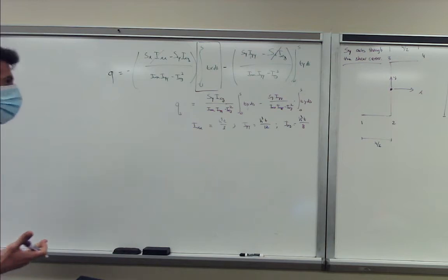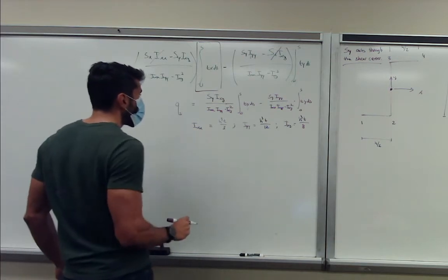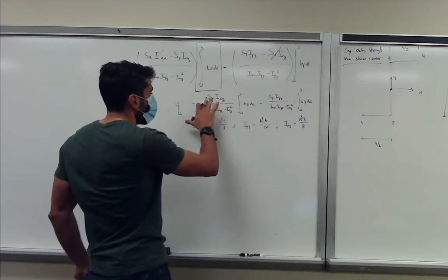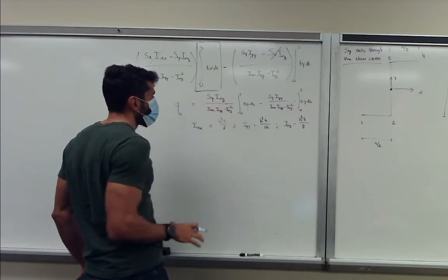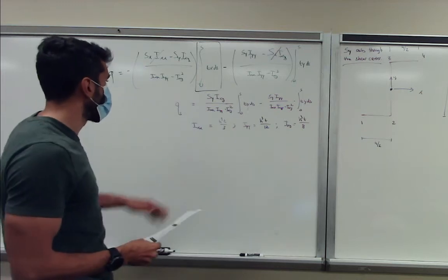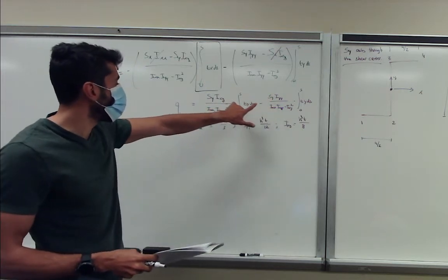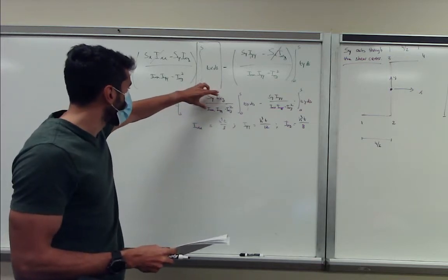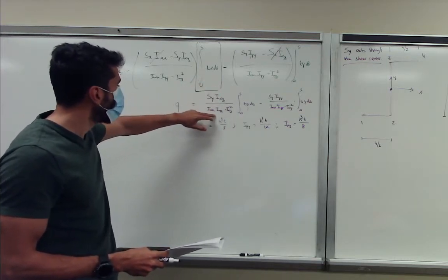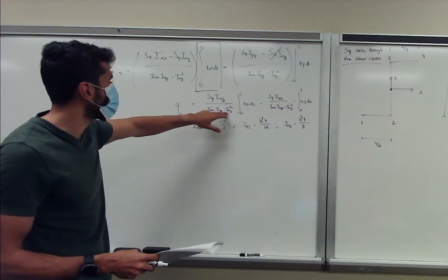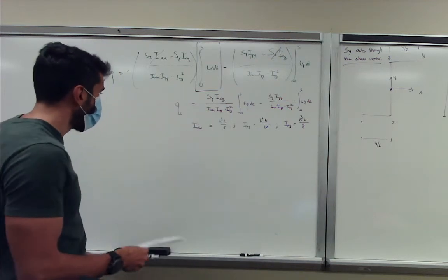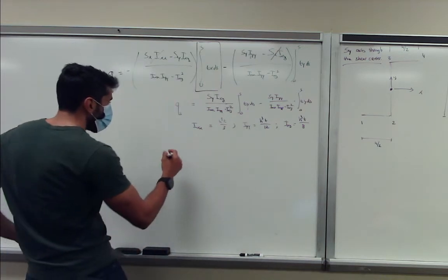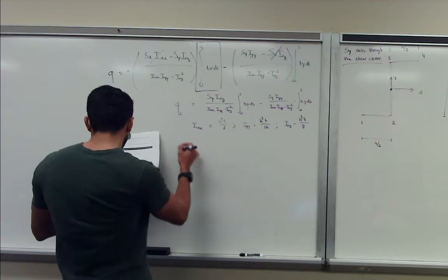So I'm going to just continue with the numbers. If we simplify that, we know that Sy appears in both parts of the integral, so we can take that out of the equation. And then we can combine Ixy over Ixx Iyy minus Ixy squared and get a number out of that. So if we do that, the equation that we end up with is the following.